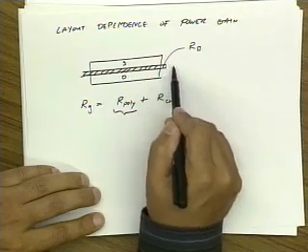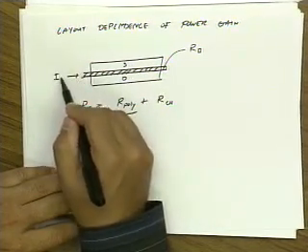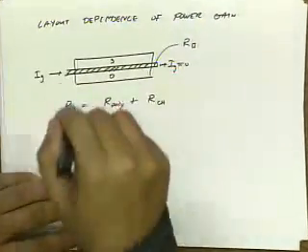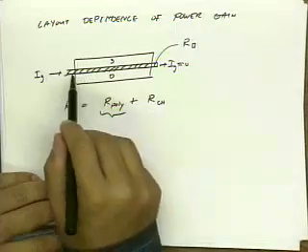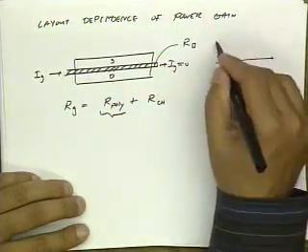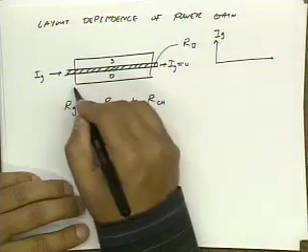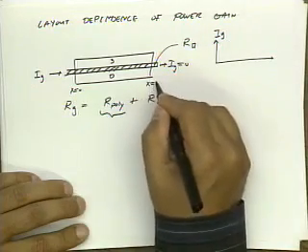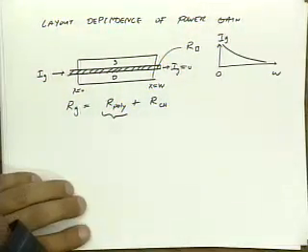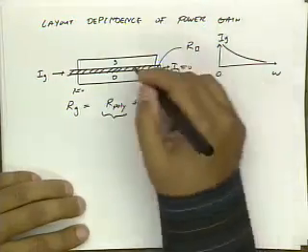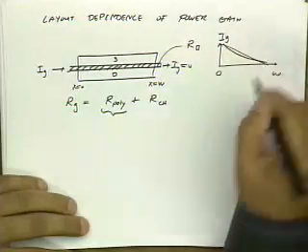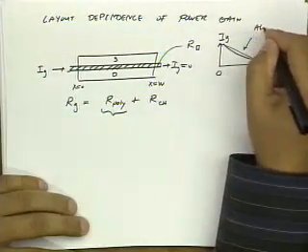The boundary condition is actually the current. So if I have I gate coming in, here I gate is 0 because I have current going down vertically into my device. So if I were to look at the current profile across this device, if I were to plot I gate from, let's say, x equals 0 to x equals W, then I would expect to see some profile like that. In fact, if this is a high quality circuit, it looks very linear. So we can say that it's almost linear.